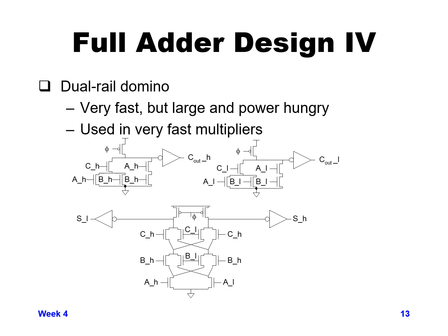Another thing to note about this type of design is the delay compared to a non-domino design. Typically the other designs might have, for the carry path, somewhere around 2 to 3 inverter delays, if we call an inverter delay our basic unit of delay, a fan-out 4 inverter.